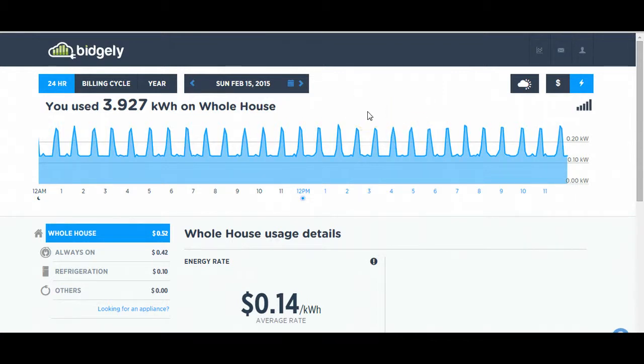So again, if I can take a look at this when I'm not there and literally nothing is happening in the house, figure out what I'm using power on and why, I can lower that baseline usage, which over time is going to save a lot of money because that's the power that's being used 24/7. So if I can reduce that, even by 50 watts or something like that, that's a serious efficiency increase taken out over an entire year.